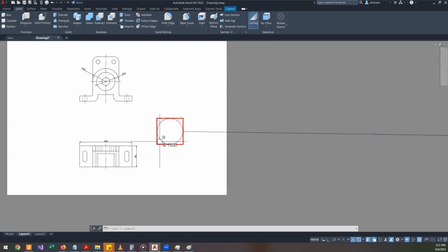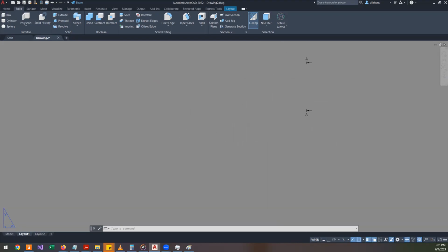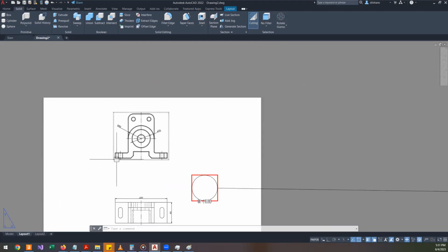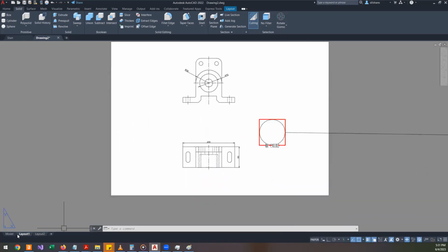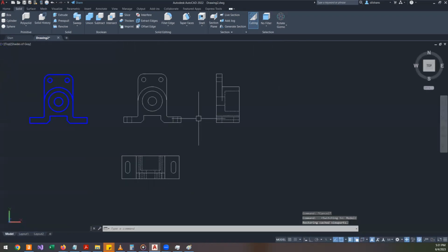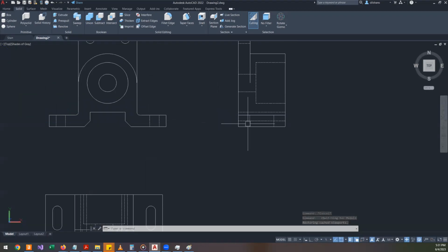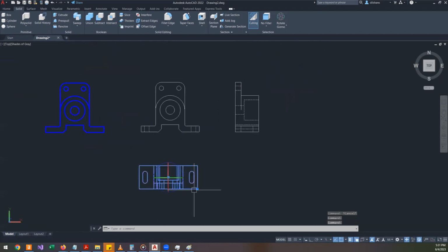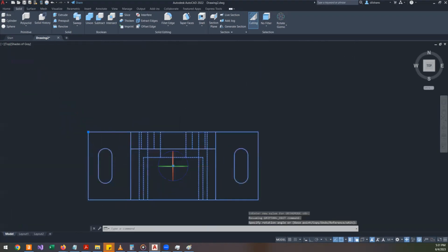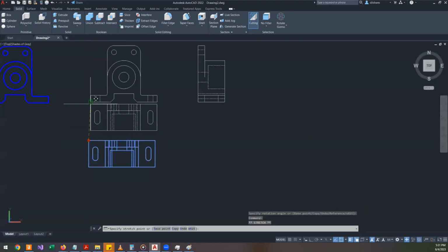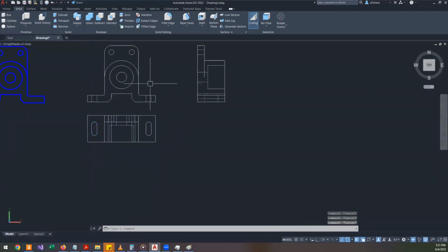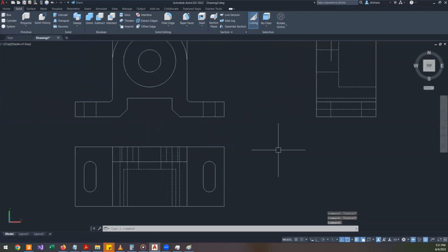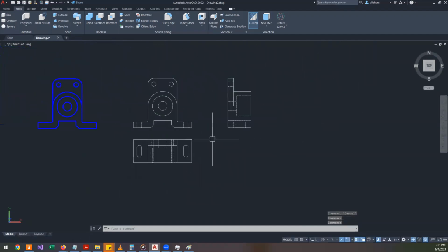If you do, this is what's going to happen. Anyway, I'm not going to spend so much time on correcting that one. I learned my lesson. Okay, that should be rotated. Like this, you need to correctly align your views. That's what the flatshot command will do.